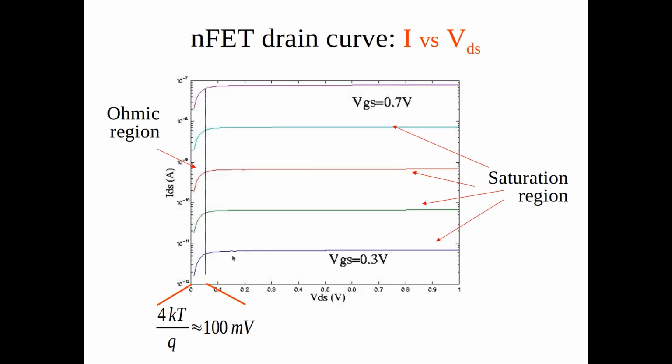That's the assumption we're making. The current only depends on the VGS. There's only forward current, and it's so small that you don't see the effect of the VDS if it's greater than 4 UT. So the current only depends on the gate to source voltage, giving you that exponential plot we had in the previous ones.